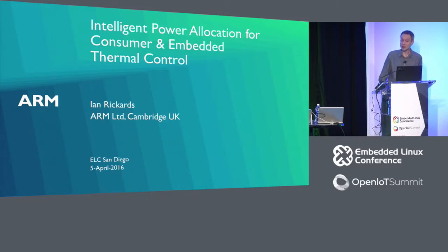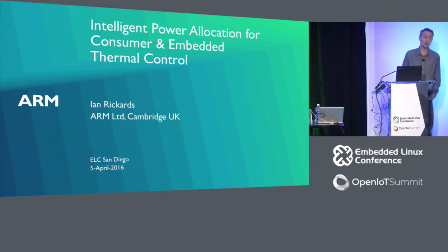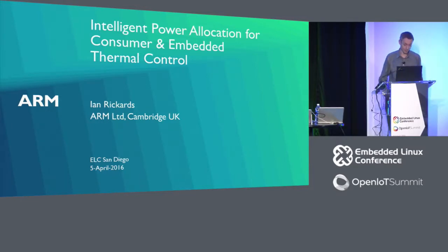So I'm presenting on IPA, which is the Power Allocator Governor in the Linux thermal framework. A bit of a mouthful, but basically this is an improved way of doing thermal control for consumer and embedded devices where you can passively cool the SoC using some features that we've upstreamed into the Linux kernel.